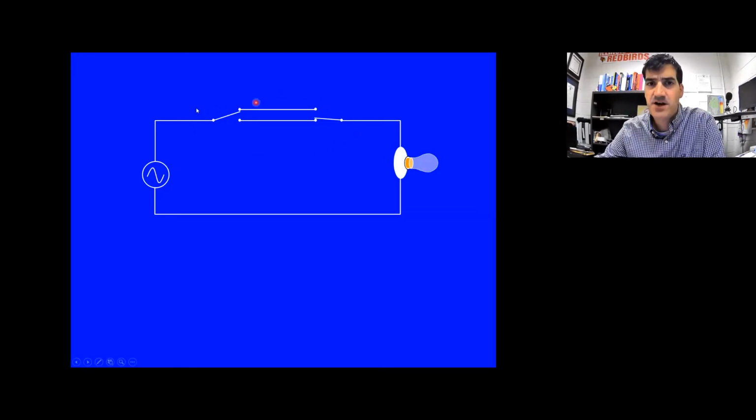All right. If you go to Menards, sometimes this is called a two-way switch. But if you look in a catalog and you're ordering one of these, I'll show you in a few minutes, they will be called a single pole double throw switch. So either one of these switches, if I change the position, then it's going to turn on the light bulb. So the left one, if I change its state, now I have continuity through this path. If I were to turn that one back off, then I break continuity. There's no way for current to flow through the light bulb.